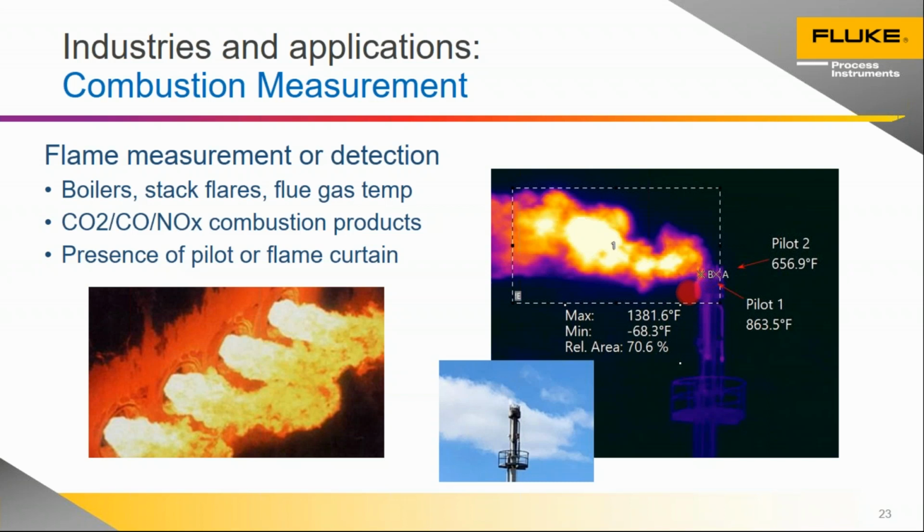And the risk here, and granted these systems, the flares generally come with a thermocouple-based system to ensure that they're on and to make sure that these plants don't suffer an event where they exhaust too much and can get fined. But those systems, since they are based on thermocouples, they can fail at times when the thermocouple fails, and it's not that easy to quickly get out there and replace them and do the maintenance at that elevated site. So having a backup system based on infrared was valuable to this customer so that they can make sure that those pilots were ignited the entire time.